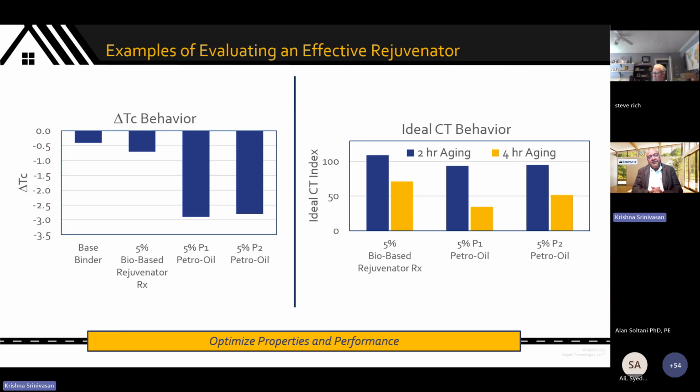I mentioned earlier petrochemical-based rejuvenators, again, useful, instructive to know why it is that they've fallen out of favor. Firstly is a flat-out case of dosage efficiency. You need roughly 2 times as much to achieve the same grade of a petrochemical versus a bio-based. Could it be 70, 80%? It's possible, but roughly 2 times as much is a good approximation. That's one. It has cost implications. Certainly dealing with some of these chemicals and oils certainly has their own implications.